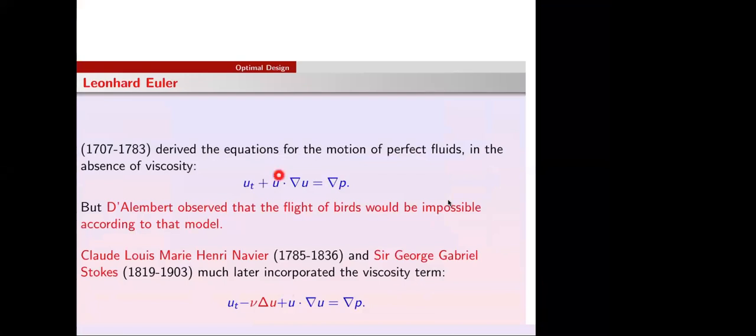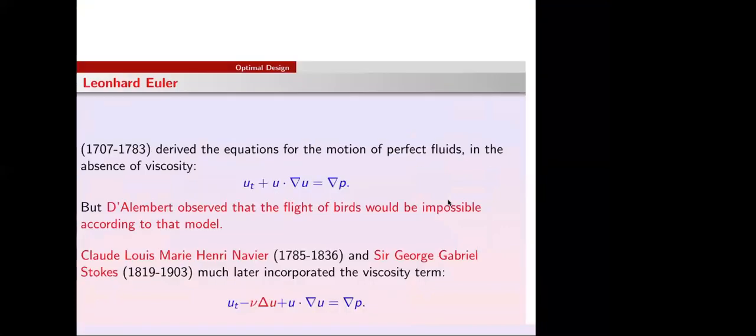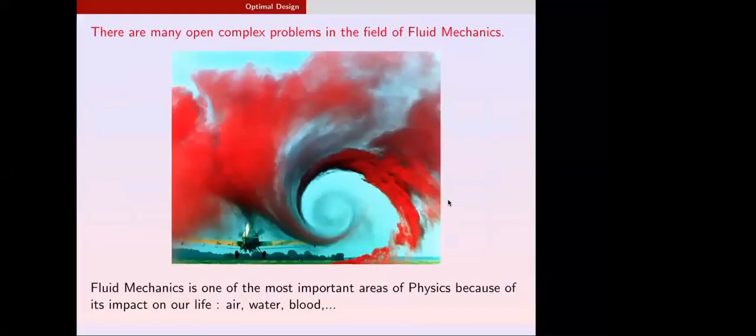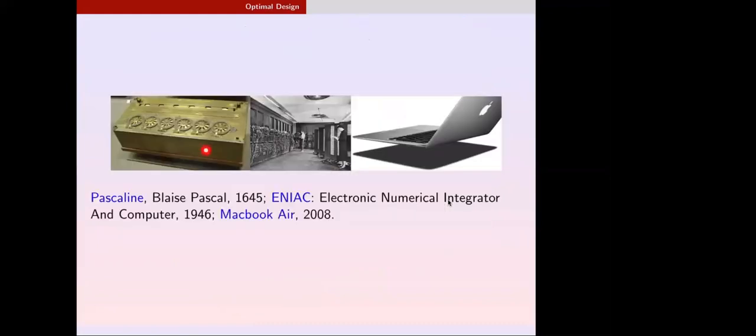And even if we don't have a completely clear picture, we can address this challenging problem of fluid dynamics, given that necessarily when we try to compute the cost functional to be minimized, one has to go through the resolution of Navier-Stokes out of the cavity omega in R3 of minus omega. So this is, of course, thanks to the computer and computer sciences and numerical mathematics and computational mathematics, right?